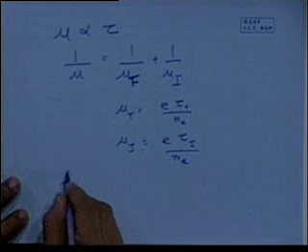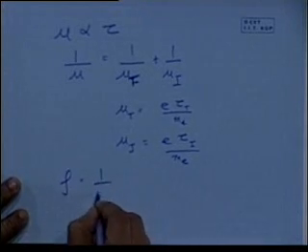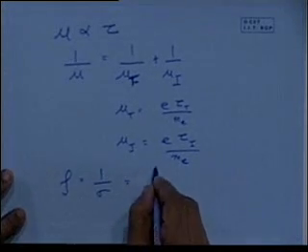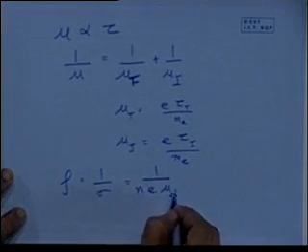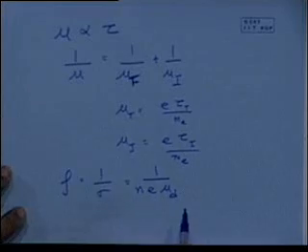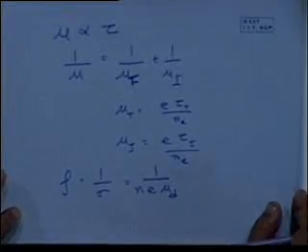So now since I know that rho, the resistivity, 1 by sigma, is given by what? 1 by Ne mu. We are using the subscript d to indicate it's a drift mobility. That's how we had, it's drifting in response to the field. So that's what's called a drift mobility, as opposed to, we'll see another term later. So we have rho is proportional to 1 by this. So now what can I write?